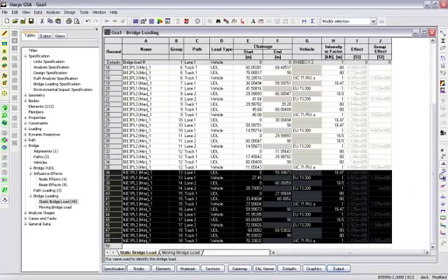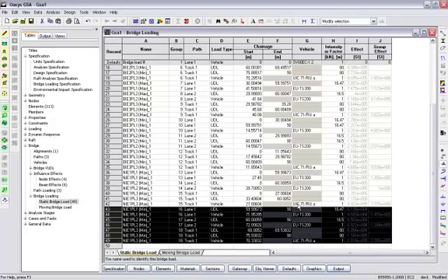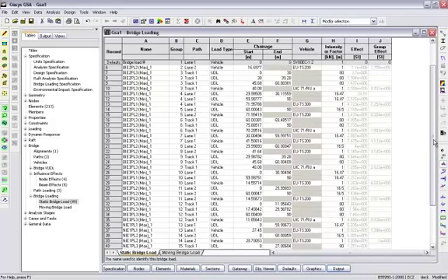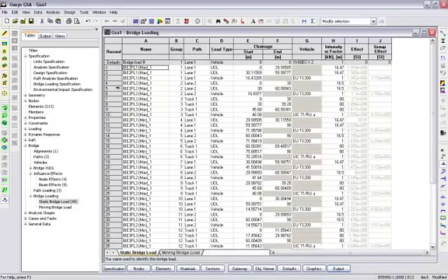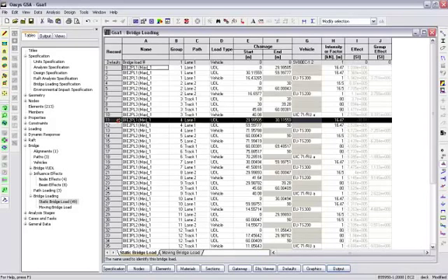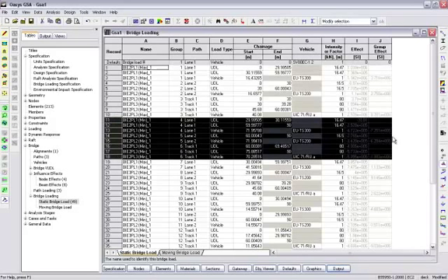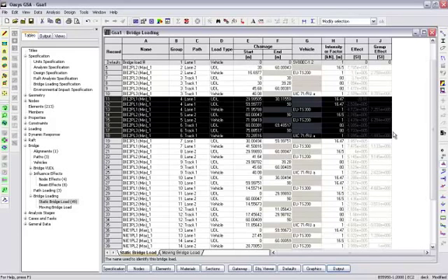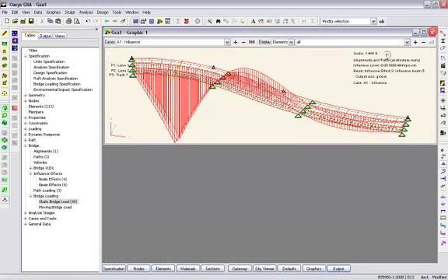Now, some of these will be unimportant. For example, I could remove uplift off the support, or alternatively I could say for the support point I want the maximum moment, but I can get rid of the minimum moment. Some of those are getting reasonably large, but you can see on the group effects column some are 10 to the 6, some 10 to the 5. The 10 to the 5 ones are going to be small, so you might be able to ignore them. I will leave all these in.